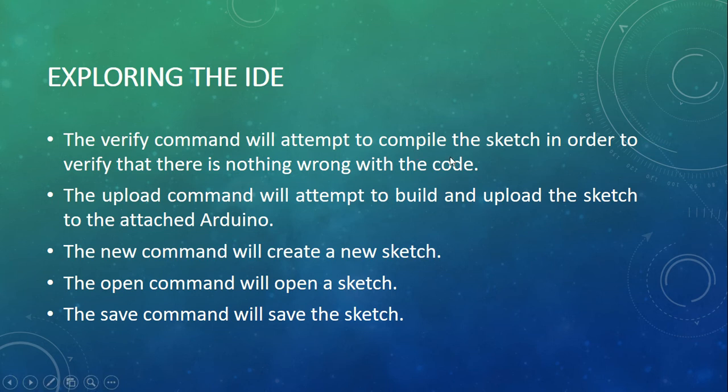Okay. One tip to avoid syntax errors in Arduino IDE is that you must really imitate the code. If it is a capital letter, make it a capital letter. And how it is written, actually, that's the secret. The syntax rules of a programming language are very strict, not like for us humans. For example, for us, a small letter a and a capital letter A are basically the same. But for Arduino, which is patterned from the C programming language, the syntax is very strict. So there is a difference between a small and a capital letter. You really must follow the syntax rules for the Arduino IDE.